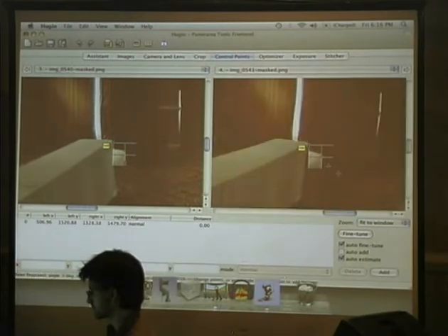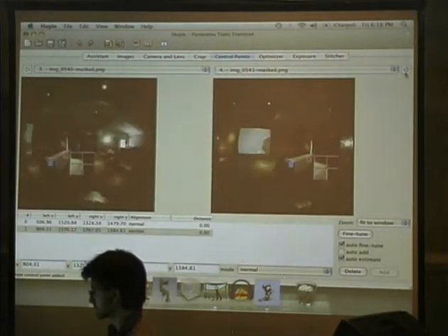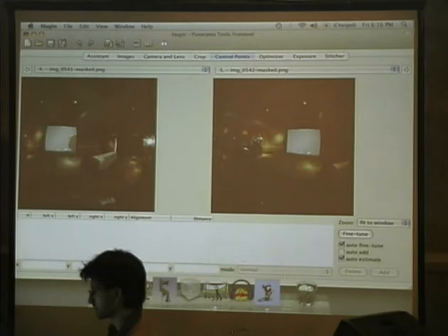So we would maybe start at a door or a place where we can determine an origin, and then move 10 feet from there, either step it off or use a measuring tape. Usually the floor either has tiles that are 12 inches, or we can just count ceiling tiles that are 4 feet by 2 feet. It doesn't have to be too exact because we're going to be moving things around in Image Modeler later. I think coverage is more important than making sure you got equal distance apart.